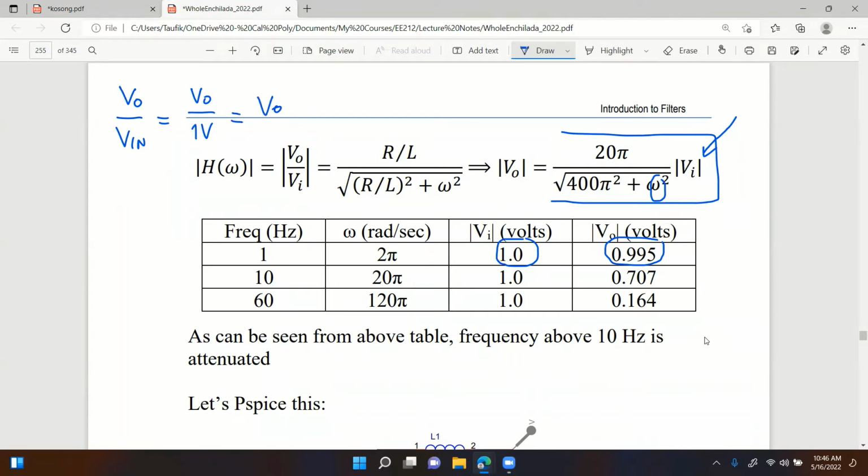In this case, it's actually the gain here. Whatever output voltage you get, that's the same as the gain, because the input is equal to 1. So it's convenient to use an input voltage equal to 1. Make sense? If you use 2 instead of 1, then you have to divide the output voltage by 2. That's more work. But if you use 1 volt, you don't need to, since any number divided by 1 is equal to the same number. That's the reason why I use 1 volt.